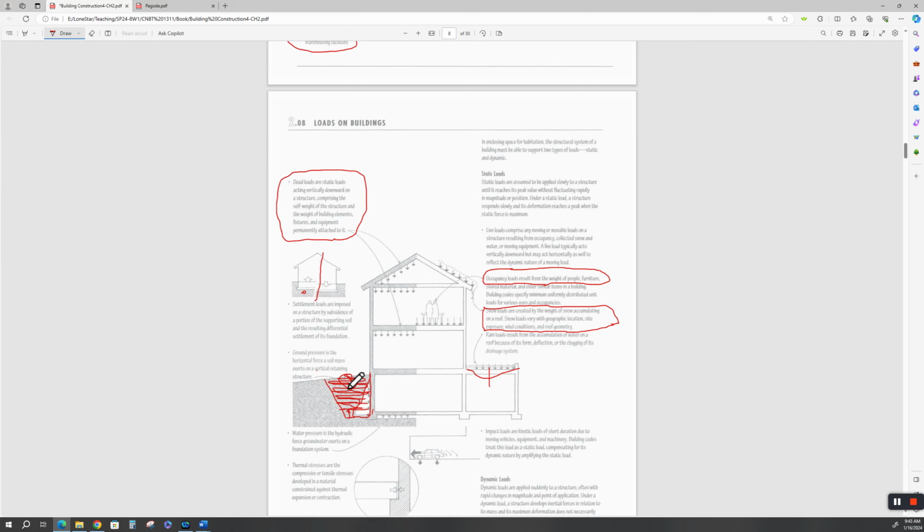And that's an additional dynamic live load, not just the weight of the soil, but the impact load and the mechanical load. It would be a live load that's pushing on this wall. So the engineer has to design this not just for the static loading, not just the dead load of this, but for all this mechanical activity going on to compact the soil, because you want that soil compacted or it's not structural.